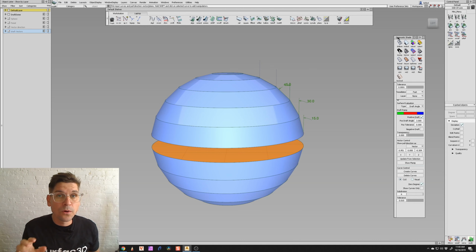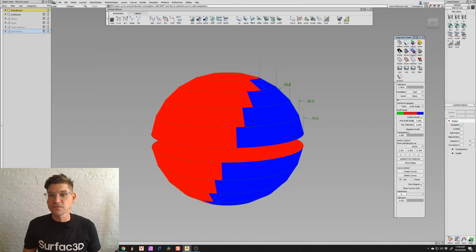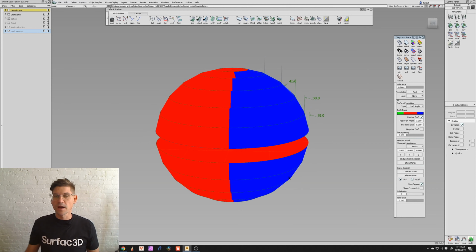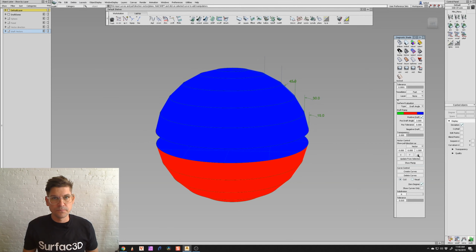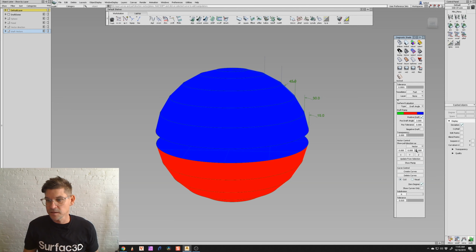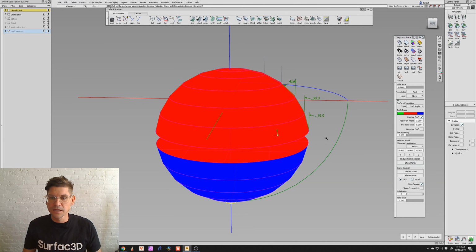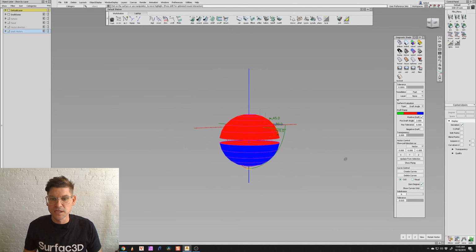It's very important to determine whether Z is positive or negative. Inside of the tool, if we just activate the draft analysis tool, I can set this quickly to X, Y, and Z. But notice the Z only gives us a positive value. So if we want to evaluate accurately the bottom side of this sphere, then I'll have to make this a negative.